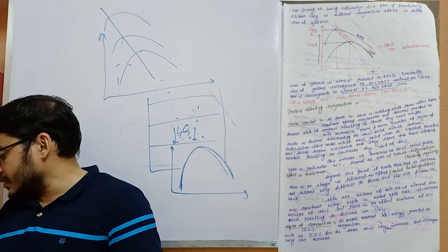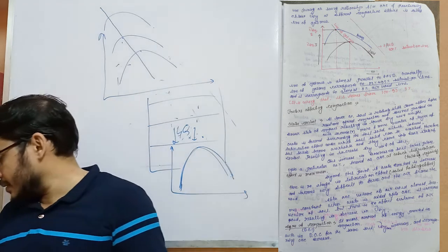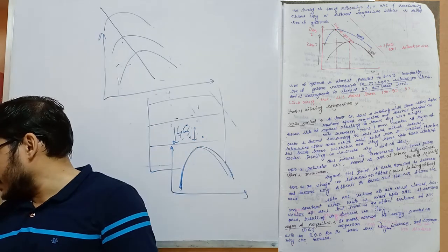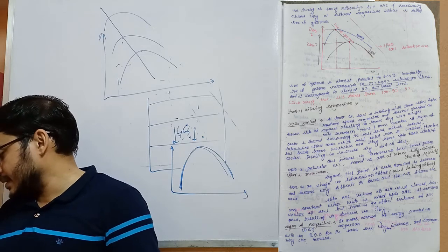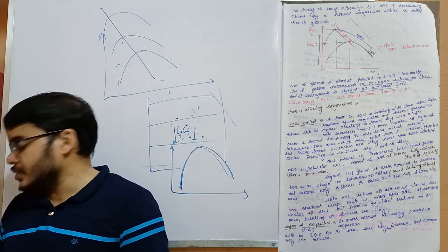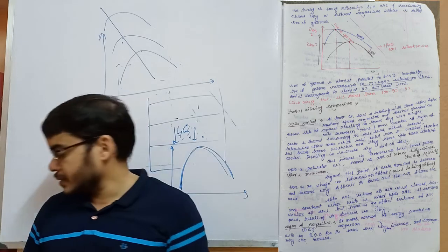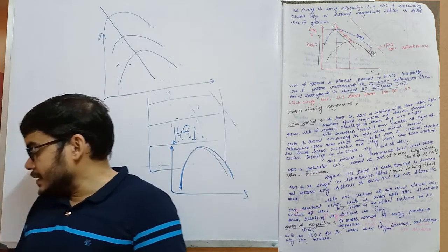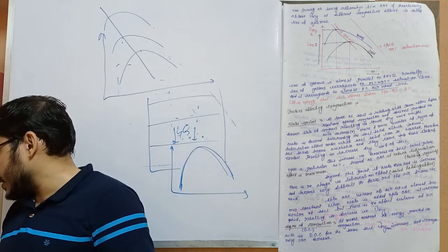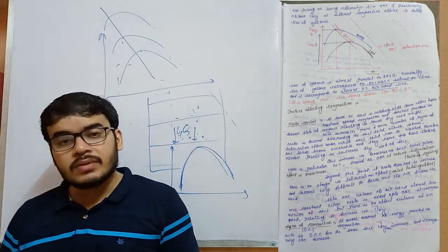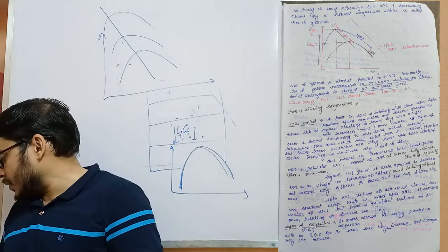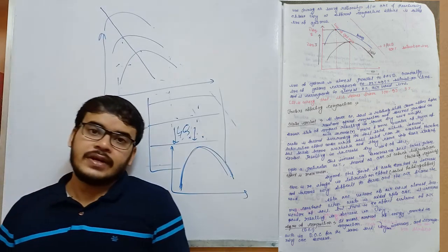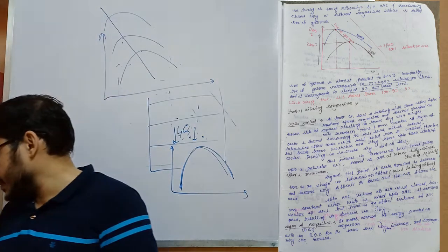Therefore, the soil solids become workable and come into a closer, denser state of contact, resulting in increase of dry unit weight. This increase in denseness takes place up to a particular water content termed OMC, at which the lubrication effect is maximum.